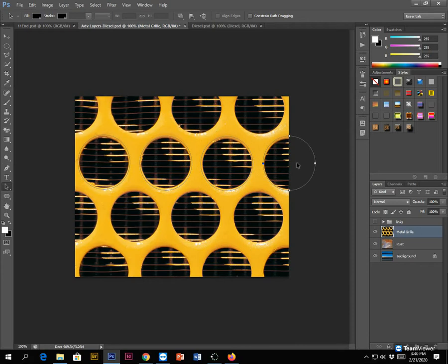All right. Now you've got 4 circles. You know how to make copies. You could just keep alt clicking and dragging circles all day, but there's a faster way to do it. We can select all 4 of these circles at once. If you take your black arrow over here where there's nothing and click and drag, it makes a selection box. Drag that selection box so that it surrounds your 4 path circles right there. Now they're all selected. Hold down the Alt key and drag all 4 at the same time.